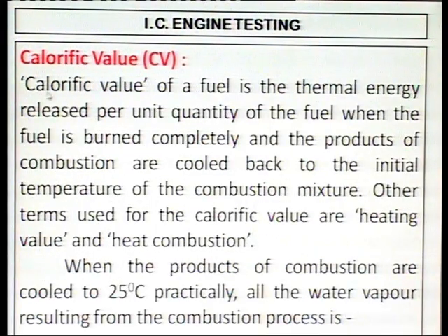Calorific value. Calorific value of a fuel is the thermal energy released per unit quantity of the fuel when the fuel is burned completely and the products of combustion are cooled back to the initial temperature of the combustion mixture. Other terms used for the calorific value are heating value and heat of combustion.